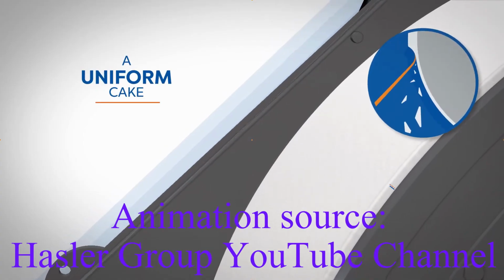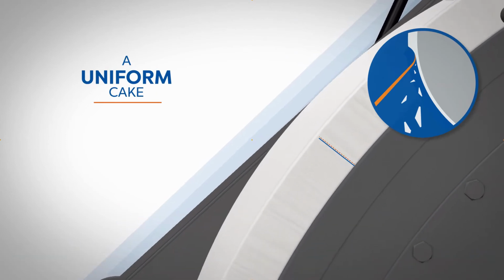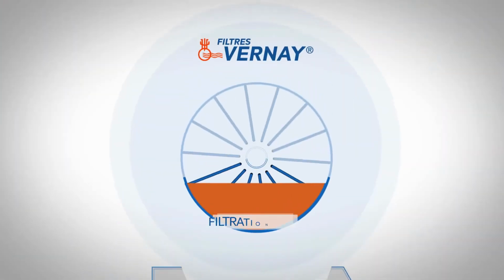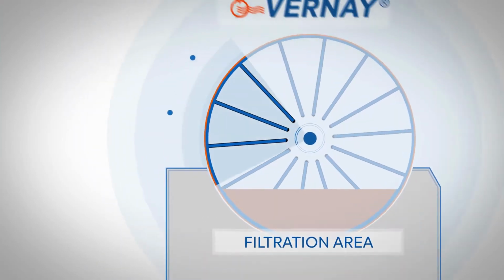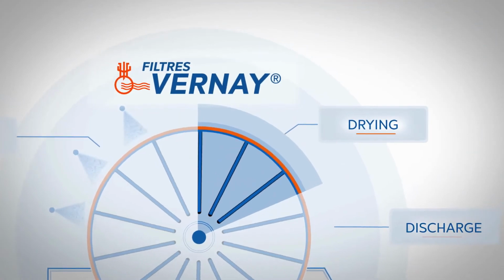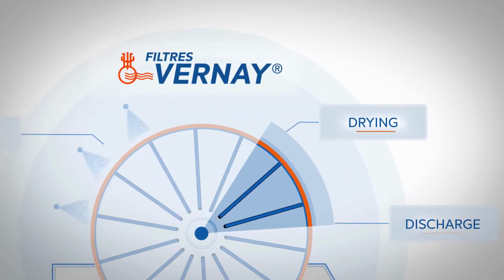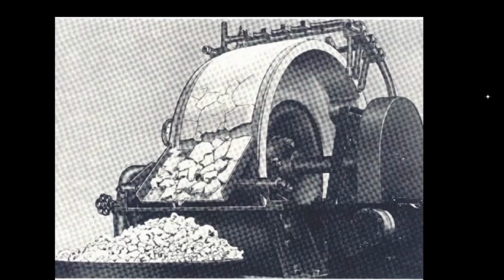A cake of desired thickness is produced by adjusting the speed of the drum. The different sectors are immersed in turn in the slurry. When the cake forms, the cake is drained and partially dried by the vacuum. The drum is sprayed with water to wash the cake, and pressure is applied under the cloth to aid the removal through a knife. And removal of washed and partially dried cake is effected by means of this doctor knife. Here is just a pictorial representation of this operation. You can see the cake formation, how the cakes are there and how it is removed as product of different sizes.